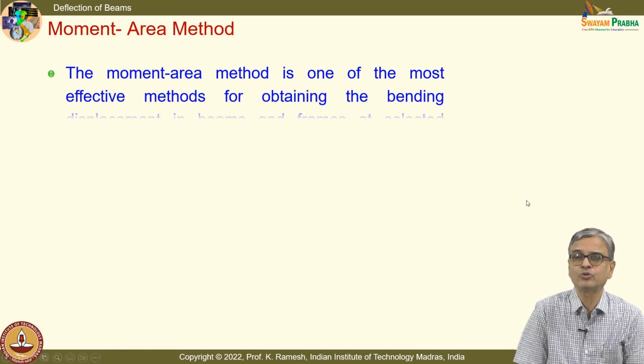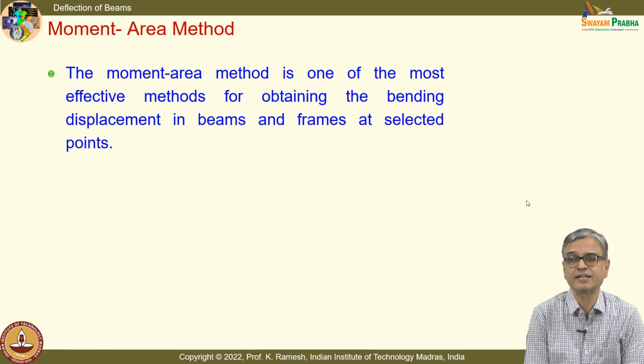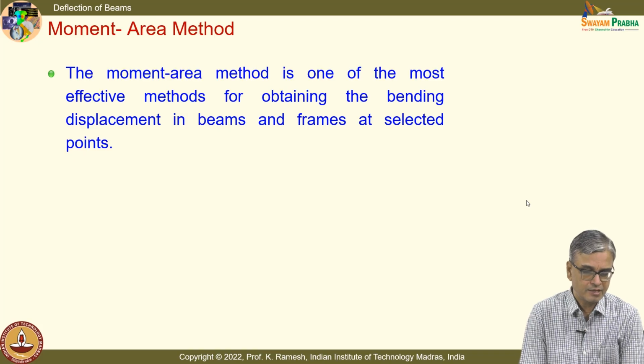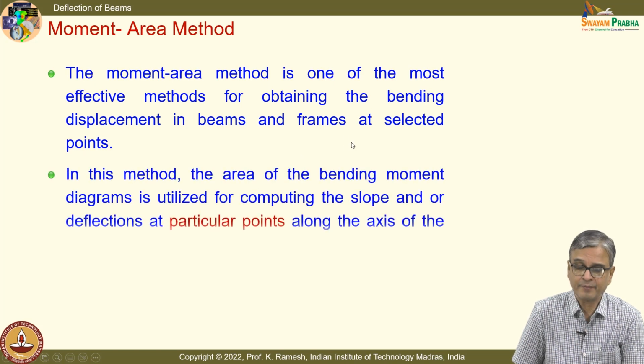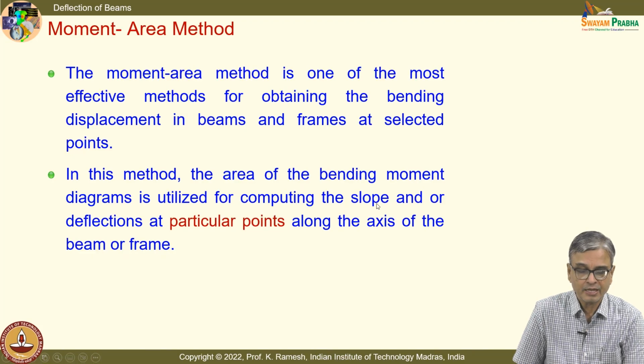Now we move on to graphical integration. I said that graphical methods are very widely used in the early development of engineering and physical sciences, and it is one of the most effective methods for obtaining the bending displacement in beams and frames at selected points. That's a key piece of information. In this method, the area of the bending moment diagram is utilized for computing the slope and or deflections at particular points along the axis of the beam or frame.